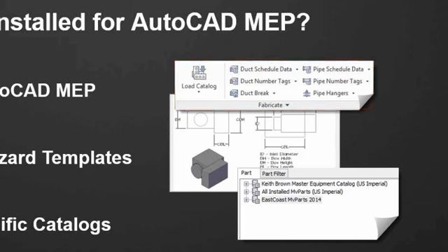If you don't have the load catalog screen, then the software is more than likely not loaded, and you can easily test that by just typing the ECDIAG command at the command line. ECDIAG, which is short for East Coast Dialog, and it'll just tell you the current version of the East Coast software that is running.